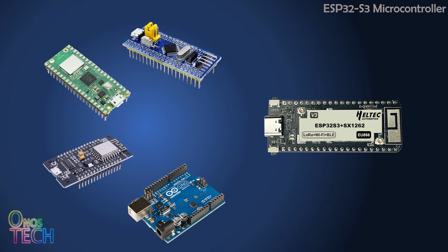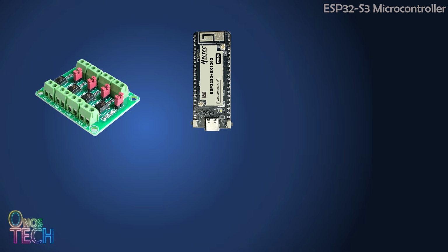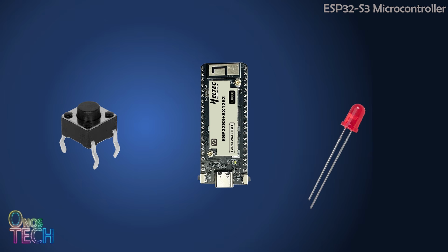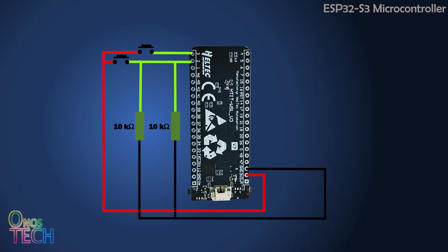into in future videos. An IEC 61131 compliant PLC requires signal isolation, such as PC817 optocoupler modules for digital inputs and relay modules for digital outputs, and operates at 24 volts DC. For simplicity, we will begin by connecting push-button switches and LEDs directly to the ESP32. For today's demonstration, we will connect two push-button switches to GPIO2 and GPIO3 of the ESP32 and an LED to GPIO4.